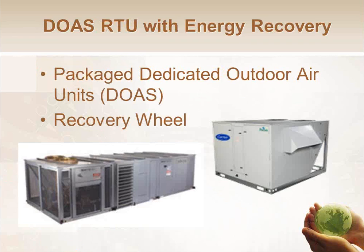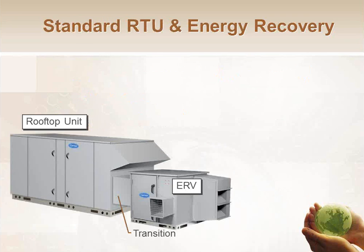I could also get ERVs built into packaged rooftop type units, or kind of like a semi-custom packaged rooftop unit. So there are some examples of that. Just a regular rooftop, but we shoved an ERV wheel in there in an additional section. So I can do 100% outside air through a regular rooftop. I could also take a regular rooftop and a standalone ERV and then bolt them together. This is attractive because I don't have to buy a special rooftop like I did over here. I can buy a regular, quote-unquote, off-the-shelf rooftop that's almost a commodity type thing, if you will, and I can put an ERV and duct them into the other guy.